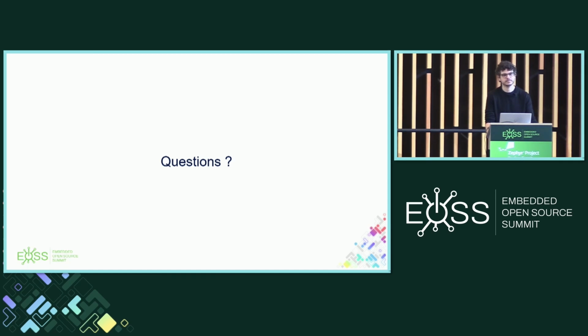In the sensor working group that we have going in the project, one of those meetings was dedicated to exactly this topic. The current API really is stateful, so you can set random attributes of a sensor. I'm going to set my sample rate, I'm going to set my range of readings. A lot of these sensors take some time to start as well, so you don't want to be constantly turning them off and on when it takes 100 milliseconds to get back to where you were.